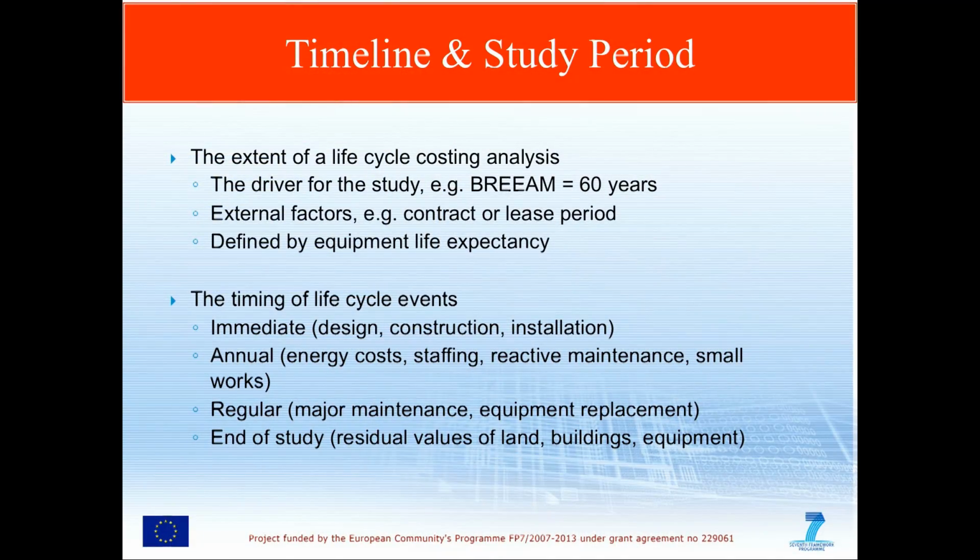Because the study period is sometimes a little bit of an artificial choice, it doesn't necessarily end with the date on which the building or the asset ceases to exist, so there will be some future use of the asset and the materials and components within it. So you can then provide yourself with some end-of-study benefits in the sense of residual value of equipment or materials, which in effect give the analysis a credit for the unused portion of the assets that are going to go on to be used in some other way.